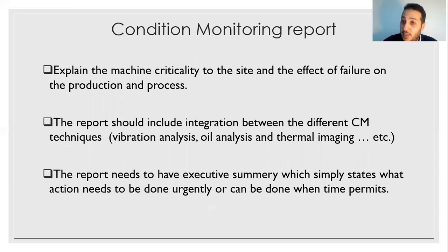Even if you don't explain this in the report, as a condition monitoring analyst or vibration analyst, you must have a good understanding of the machine criticality and how important it is to the site. And whether you need to take immediate action by reporting by phone call or email, or you can wait until the routine report time comes. The report should include integration, especially for the commissioning reports, between the vibration analysis, oil analysis, and thermal imaging.